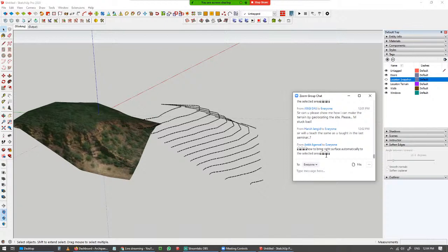Can you suggest some other extension similar to Artisan, because that extension is not working for me? Other extensions like Artisan, you won't get all the tools of Artisan, but individual tools are available. Like instead of the sculpt brush tool, you can use the smooth tool. They work more or less similarly. And if you are working with other tools like subdivide and smooth, you can try other tools like, again, that will be a paid tool called SubD.